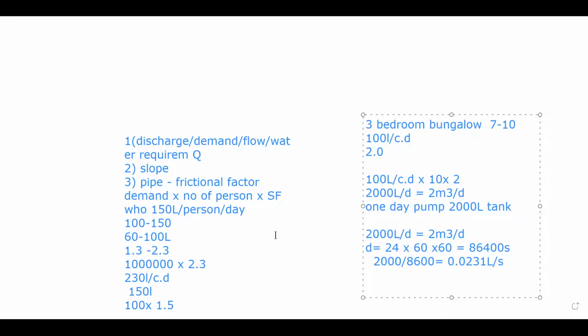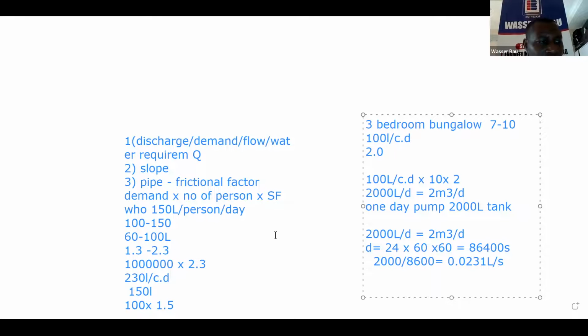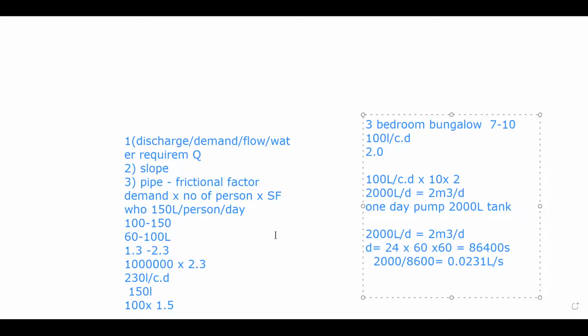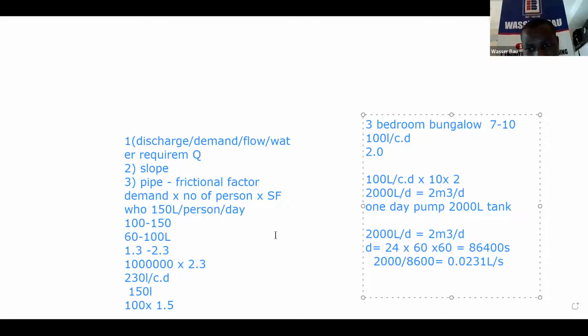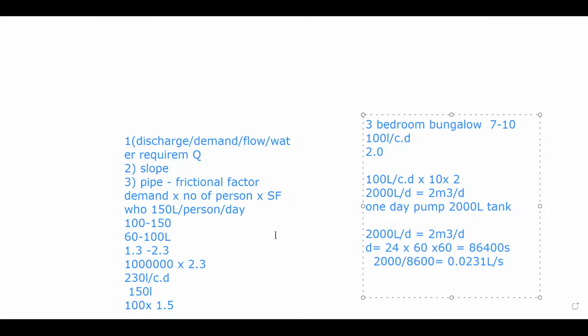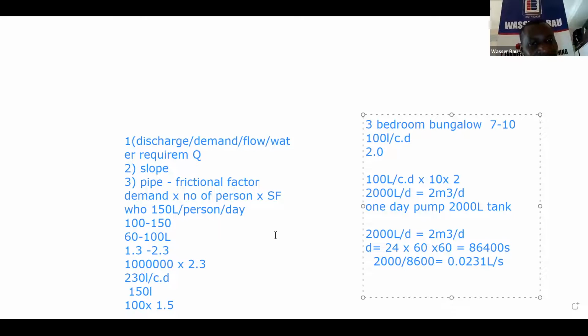Thank you. You just used the word that I want to re-echo: over designing. In many infrastructure designs, especially water or any underground design, it is advisable to over design than under design. Under design is a colossal loss. Over designing is just extra money. So to start with, over designing is allowed in water reticulation systems because the system can only grow.